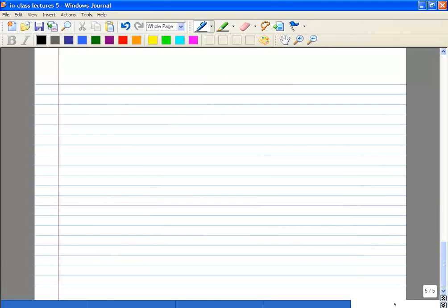Okay, so let's look at what kind of capacitances do you have. You're interested in, let's say, drain bulk and source bulk capacitances. The other things are all, for example, gate drain and so on, or source drain. They are all related to your overlap gate, and gate drain or gate source overlap capacitances. So you can't do too much about them. That's limited by the process. But the junction capacitances, you can do something about them. If you look at these junction capacitances, they actually have two components.